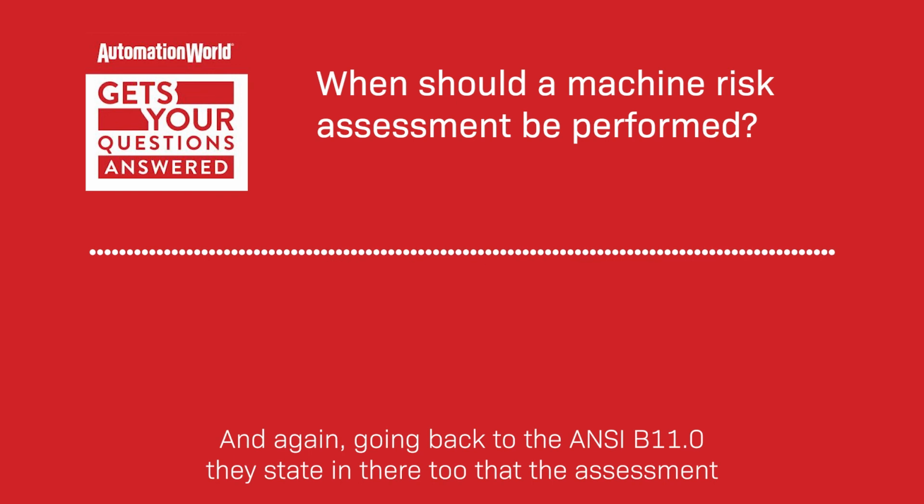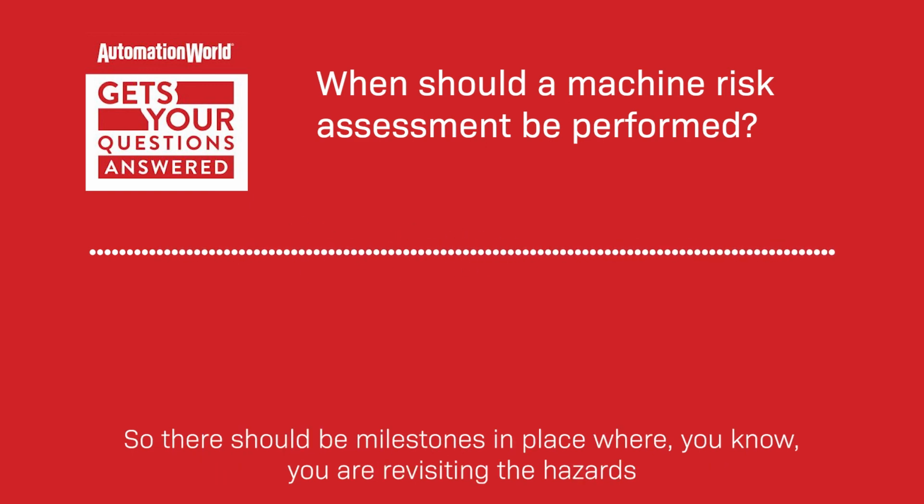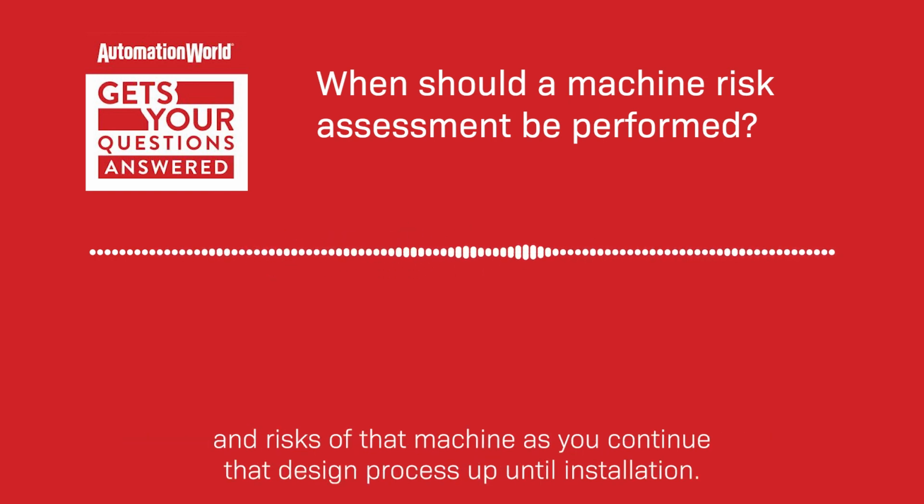And again, going back to ANSI B11.0, they state in there too that the assessment should begin as early as possible, and then be updated and validated as the design matures. So there should be milestones in place where you are revisiting the hazards and risks of that machine as you continue that design process up until installation.